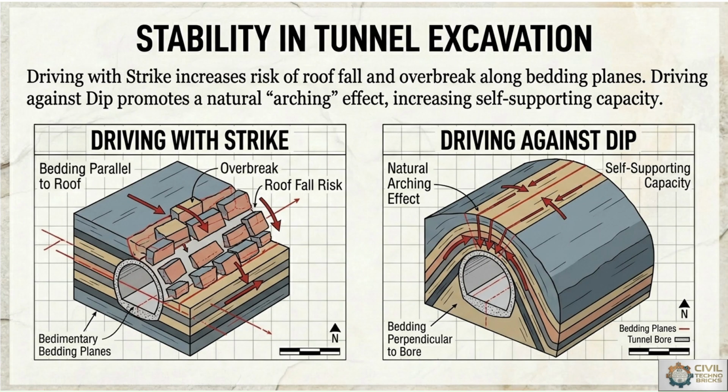Sedimentary bedding planes are parallel in image 1. At the same time, in image 2, we can see the bedding perpendicular to the bore, that is the orientation of the rock masses. Here a natural anchoring effect is there. The self-supporting capacity of the bed rocks is also mentioned. So driving against dip and driving with strike show the stability in tunnel excavation.